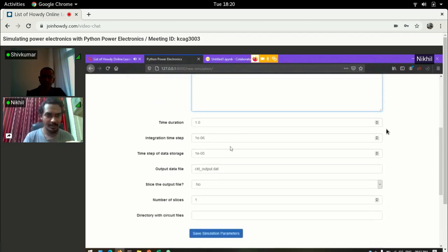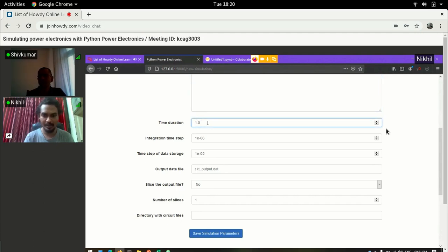Also, this time duration we are initializing first, can we give it a variable name so that we can declare it in the script? No, this has to be constant. You have to give a proper value. Okay, by default we can give 3600. Then the sample size: since it is a long simulation, should we increase the step? Yes, you can make it 1 millisecond.